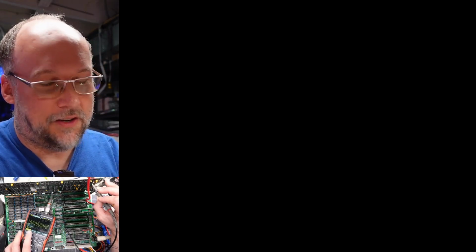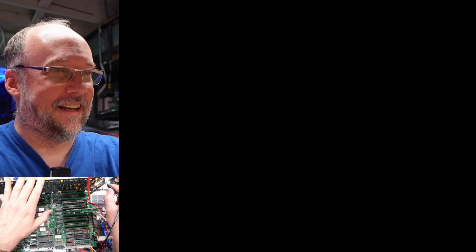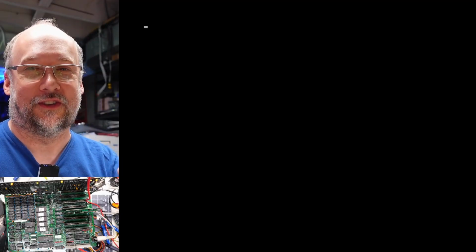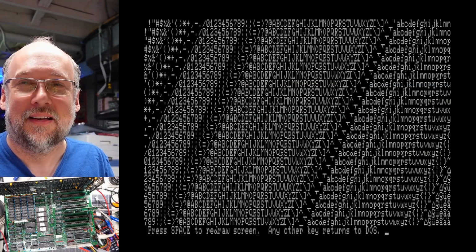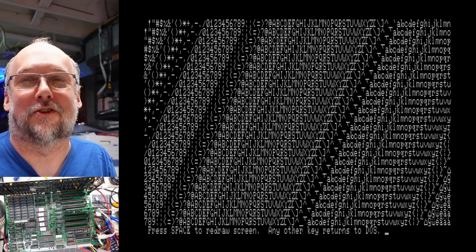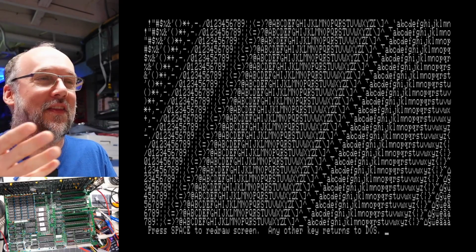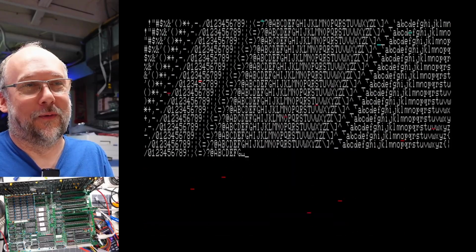Okay, let's just take a look at what that signal looks like with the oscilloscope now. All right, definitely have it on 14 megahertz. There it is, the signal going into it, 14.3 megahertz. Too fast, I guess. That doesn't work. I'm gonna look around for slower clock speed than 14 megahertz and see if I can find one that actually works. Alrighty, I got it. I just hooked it up to an adjacent pin that was like 3.47 megahertz, whatever the NTSC clock is. And instead of 14 megahertz, it freaking works.